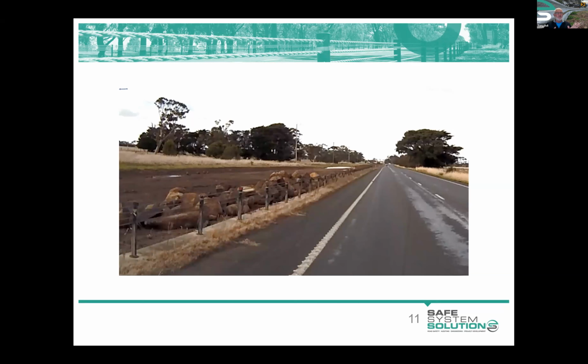And this is a really great example of what an audit should be able to pick up and say, well, hey, you've created this hazard. They're too close to the deflection, or it's within the deflection area of that wire rope. So therefore, there should be something done about that. So in addition to your signs and devices and the like, because of the roadworks, it's actually introduced a hazard to the road users.